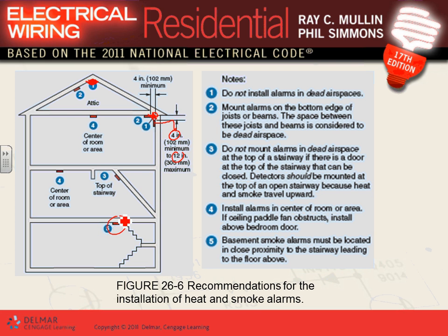The reason why we put them closer to the stairway in the basement is because they can also indicate the location of the stairway. If there is a fire, you shouldn't be sleeping in the basement, but if at night you're in the basement and there is a fire, the fire alarm location will lead you to the exit of that area.